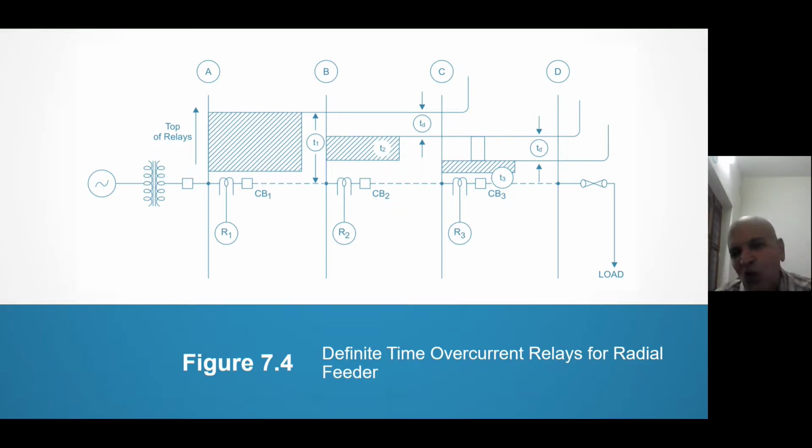So now you see, all the disadvantages of instantaneous overcurrent relays are gone. In instantaneous overcurrent relays, we were not taking care of thermal capability. Here, you are taking time in tripping. Therefore, you are exploiting the thermal capability of the equipment. You are taking care of the instability of the generator. Backup it is giving. R2 is giving backup to R3 because R2 has to reach up to D.